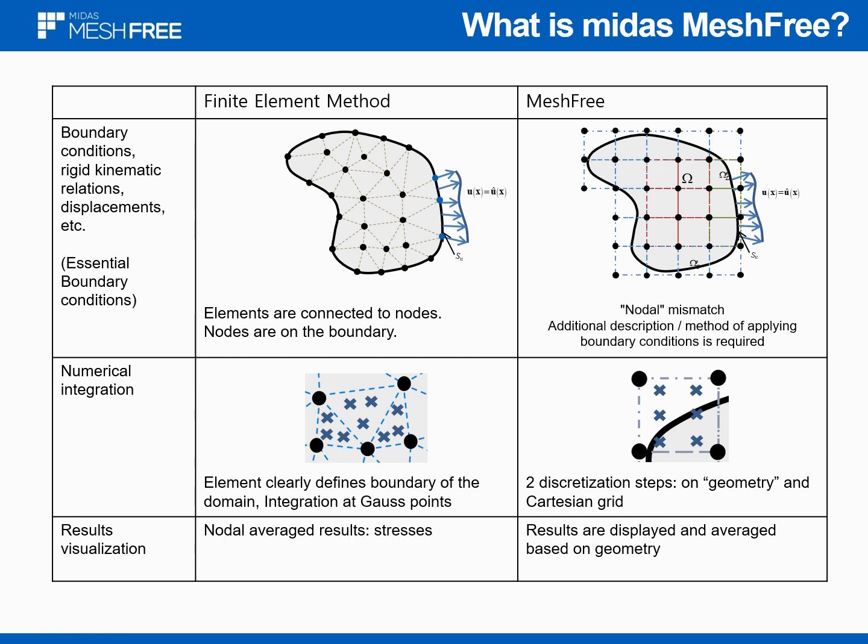The second challenge for accurate calculation is obviously accurate integration. For immersed boundary mesh methods, the geometry representation, which means the boundary, is shifted from the finite element mesh to quadrature points directly. The essential idea is to simplify the mesh generation process by separating the solution from the geometry representation of the domain.